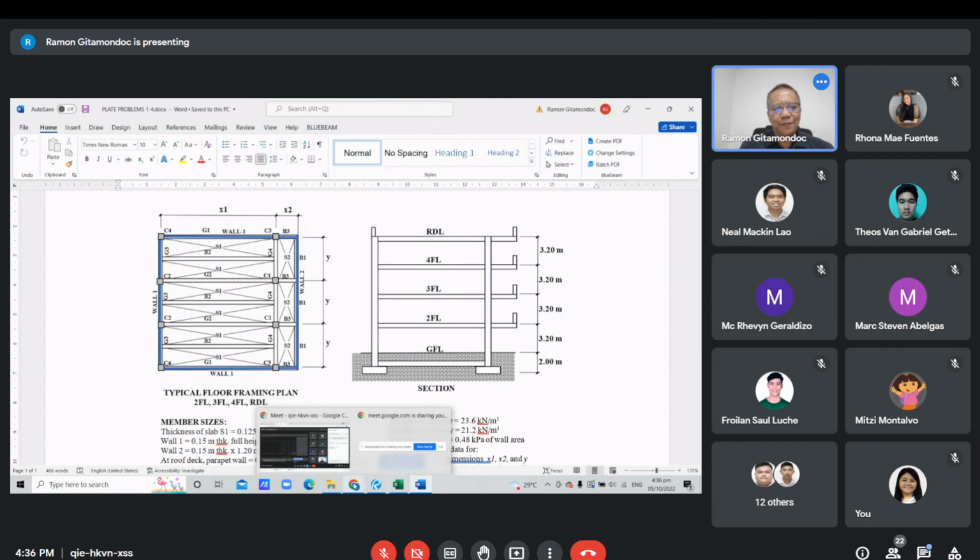Thank you, sir. Okay, so it's clear? Yes, sir. The reason is that on these sides, wall 1, wall 1, wall 1, these are property lines already, no? So imagine the building is situated in a commercial area, here in Colon. The frontage is at wall 2, so you can have windows there, but at the sides and the back it is closed, no? Firewall.